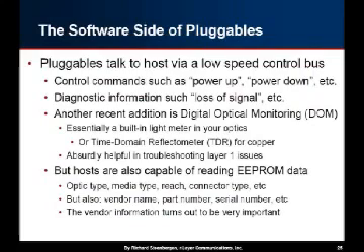So there's also the software side of pluggables to talk about. Pluggables talk to the host via a low-speed control bus. That's a lot of commands like power up, power down. There's diagnostic information, loss of signal, whatever. There's the big one, which is the digital optical monitoring, which is great when you're troubleshooting layer 1 issues, because you can now see what the power is on a particular circuit that might be going bad without having to dispatch a tech and train them how to work a light meter.